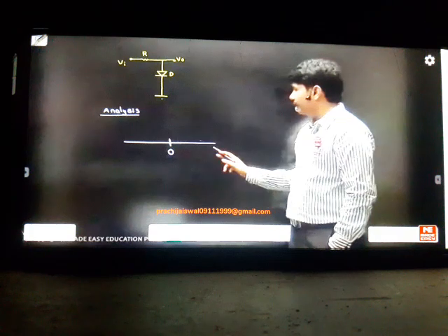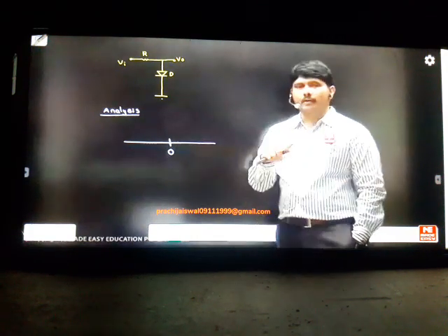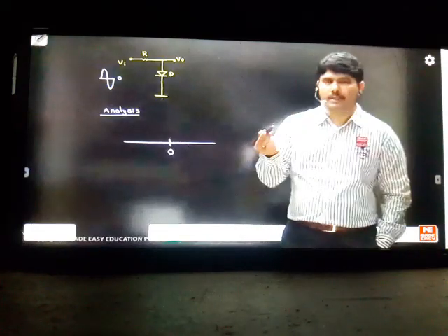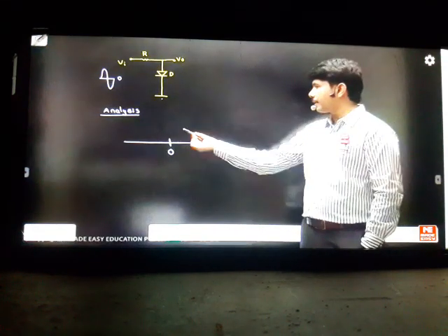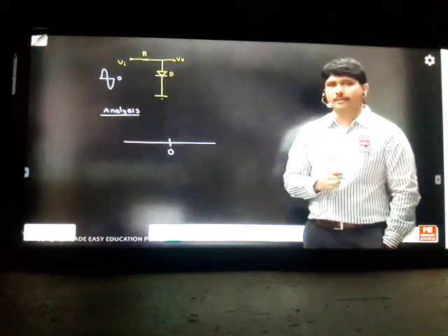So from here to here we have a reference 0. First you mark that point. After making that marking you have to understand this diode can be on, can be off. How many situations can we see? If you apply a sinusoidal signal with 0 as the DC level, your signal can go above 0 and can go below 0. That is the point we are seeing. Signal can be above, signal can be below. So I understood that the diode can have two statuses, on or off. These are the two points you first justify in your concept.